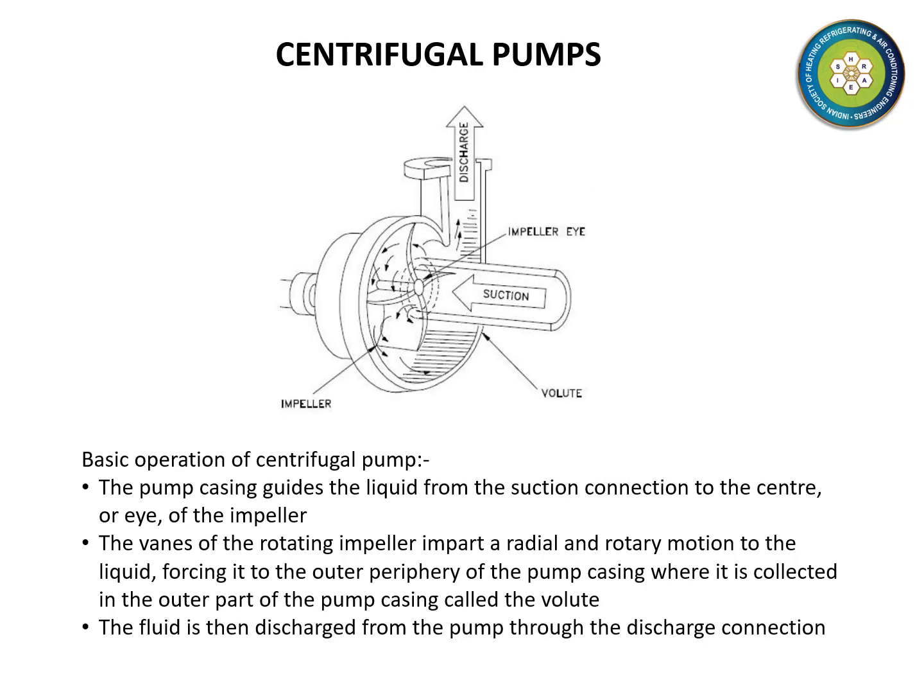The basic operation of a centrifugal pump is shown on this slide. The fluid is sucked into the center or eye of an impeller rotating at high speed. The vanes of the impeller impart kinetic energy to the fluid, which is then discharged from the pump as shown.